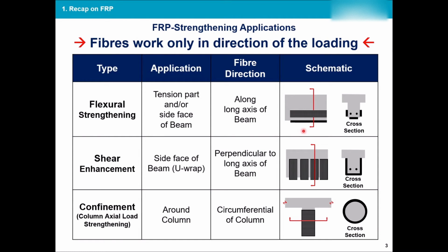On the other side, remember that FRP only had elastic behavior and it was only in tension, no compression resistance at all. That elastic behavior had very high elasticity and high final strength as well, but when it reaches its ultimate point, there is a sudden rupture because it's only elastic. It does not have any nonlinear, plastic or ductile behavior.